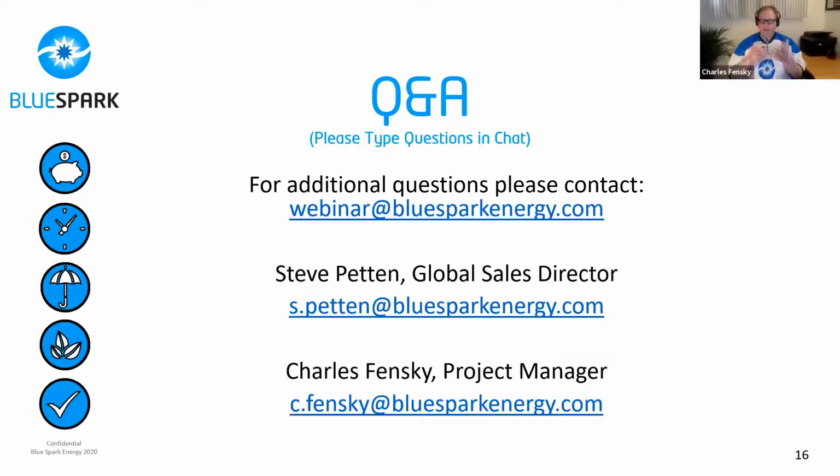And so the item you have to look at is there's 2 different types of material. You have a brittle material. When it actually sees a wave, it can't absorb that energy and it'll crack and break. Where you have a ductile or more elastic type material, it can absorb that energy over a period of time before it breaks. The other key thing about these shock waves is they happen in very, very small amounts of time. So you'll get that burst, but it only lasts for a few microseconds and then it's gone again. So that ductile material, such as the metal, can absorb this without deforming or having any issue.